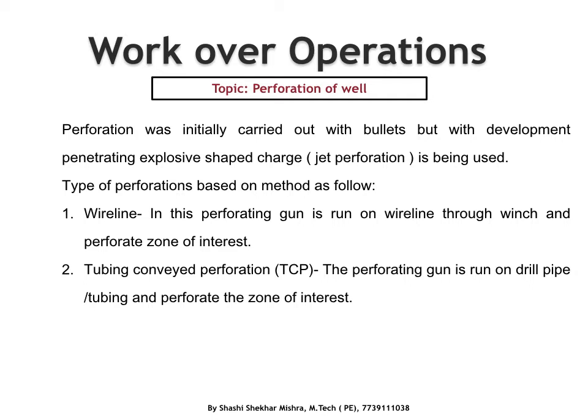If the plan is to do shoot and drop, and there is enough room for the gun to be dropped in the sump, we go for TCP shoot and drop. The advantage is that we directly perforate the well underbalance and immediately put it on production.